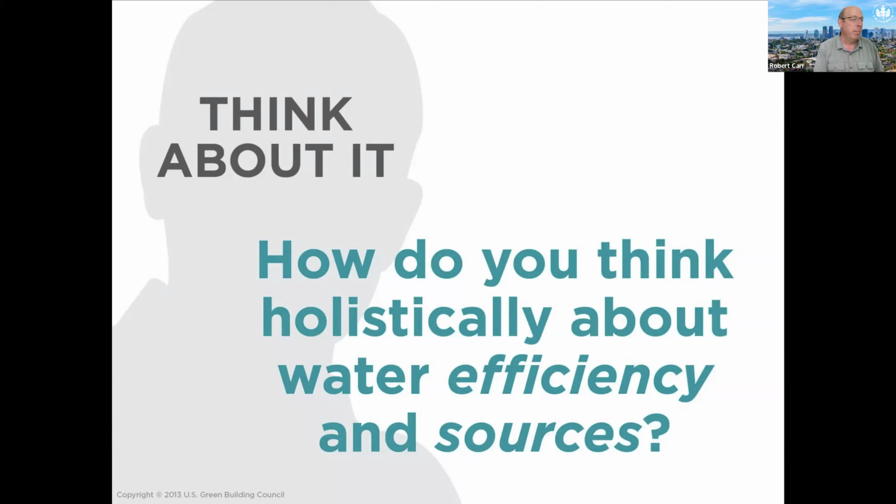And then RA is saying metering and sub-metering, absolutely. If you don't know how much you're using, it's hard to manage that. So if you can sub-meter, like our bathrooms, our cooling towers and stuff like that, you can really understand where the water's being used, and then you can make decisions on how to reduce it. So that's definitely a case as well. All right, good, thank you.